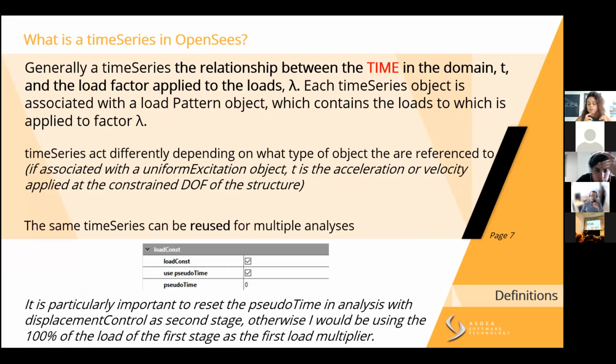So this can be quite confusing because these are the same concept in OpenSees. In other software, these concepts are separated. There are different commands to apply accelerations and other commands to apply load factors. Instead here, the command is the same one, to define the behavior that you want your analysis to have. The same time series in OpenSees can be reused for multiple analyses.